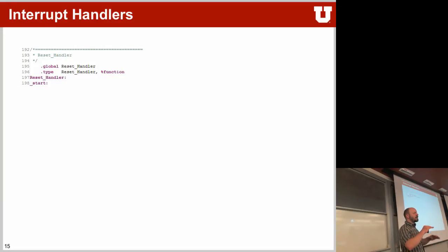Like in C code, if you write int main, you expect that's where the code starts. No, that's not true. The code really starts executing in the reset handler. And I encourage you to go and find this file and look at the reset handler to see what it is doing. Because what it's doing is initializing memory. It's writing zeros into memory locations, into the BSS section. And then at the very end, it jumps to main, where it starts execution.